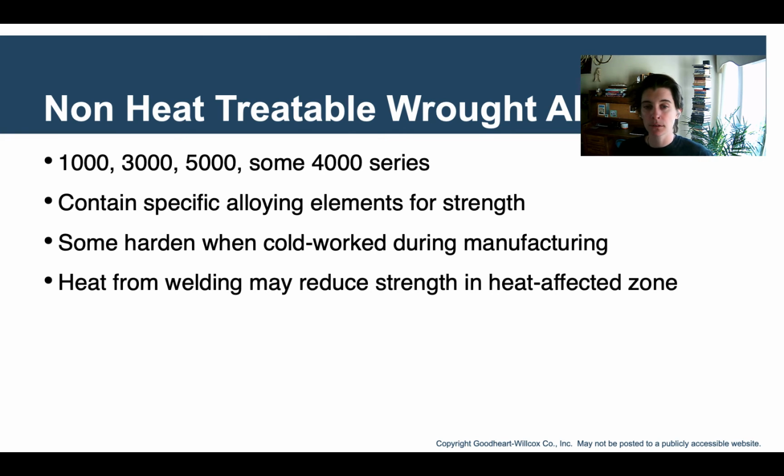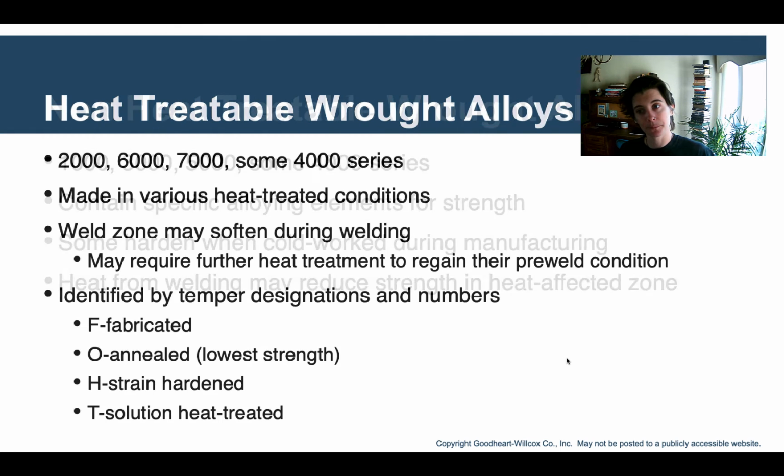So the heat from the welding may reduce strength in that heat affected zone, and you can't bring that strength back. So it's just things that you have to think about and remember with these alloys.